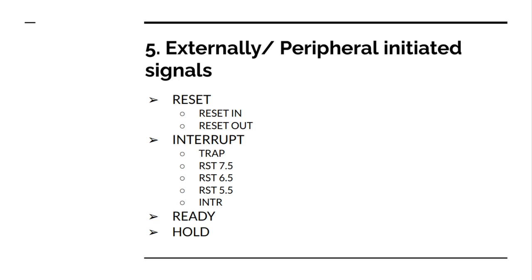Then we have the externally peripheral initiated signals, that is the reset in, reset out, interrupt, ready and hold. These have certain uses, so let us learn about each.